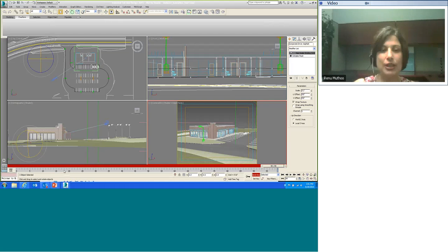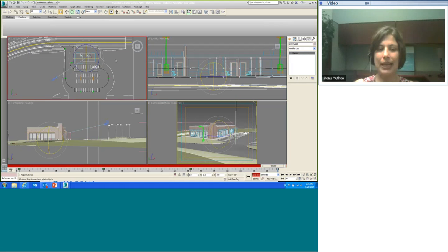So we need to select the dummy object, and here you go. When you select the dummy object, you will see the keyframes. You can add animations of different sorts on different objects and then play them in conjunction. And if you want to make any changes to a certain animation on a certain object, you need to select that object first so that it displays the keyframes for it.